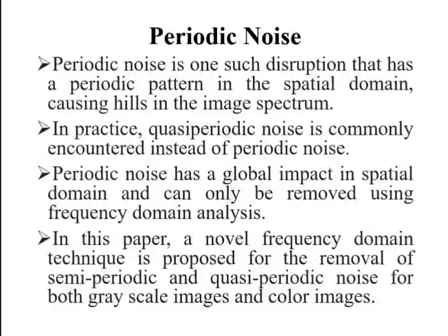Then the next topic is estimation of noise parameters. The noise parameters are estimated by using selected weak texture patches from a single noisy image. Experiments on synthetic noisy images are conducted to test the algorithm, which show that our noise parameter estimation outperforms the existing algorithms. The parameters of periodic noise typically are estimated by inspection of the Fourier spectrum of the image.